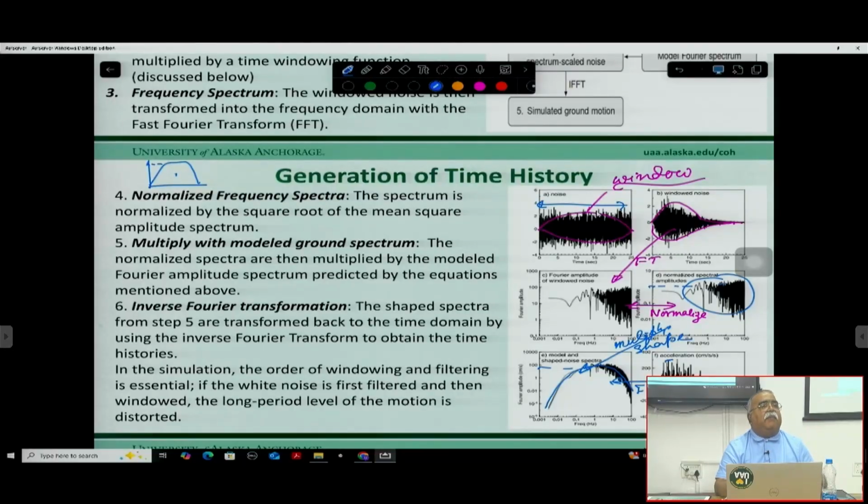So instead of not having anything else, at least with this magnitude, with this range, and with this shape, I can generate a comparable type of earthquake and try to take a lot of realizations, and then we can generate a suite of time series, and from this suite of time series, you can calculate the average values either in PGA or PGV or in response spectra, and you can compute the mean values and standard deviation so that you have a fairly good idea that this magnitude of earthquake at this much of distance can do it this way, right?